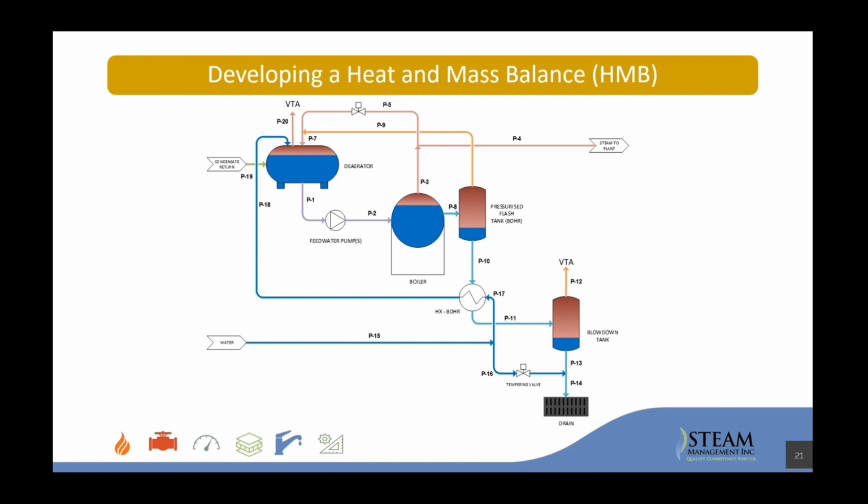So you have surface blowdown going in. It will flash off to steam, and you can use that steam in the deaerator. Even though this is dirty boiler water, the flash steam flashes off clean, so that can be used. And then the drain will go through this heat exchanger here and basically preheat makeup water going to the DA. All of your water lines are in blue, blowdown lines are in turquoise, and steam is in pink and orange. So that's the system.